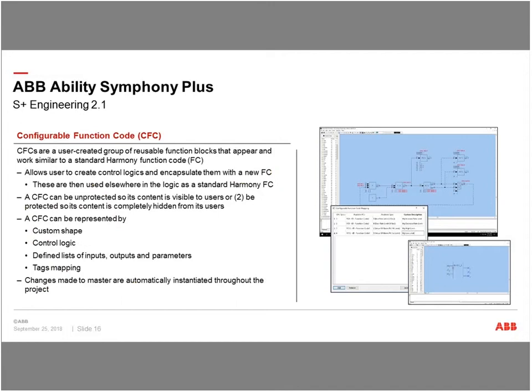So here just shows some examples for CFC. Later we will give a more detailed demo. But basically, you just configure your logic, and then you can also design your shape, and the inputs, outputs, what's the original point, and then you can map the inputs to your CFC, to your function code, and output, and also spec. You can hide some spec. They are not exposed to your user, but you can also expose certain spec to be able to be configured by your user later.